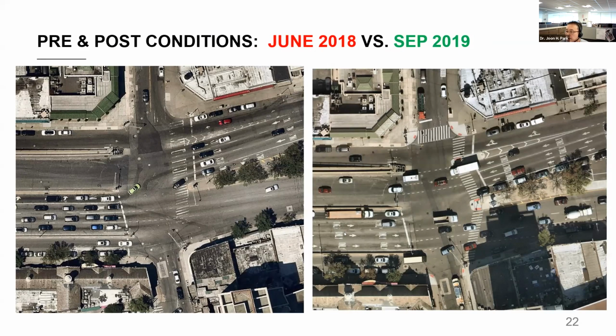This is a bridge location, so so much congestion creates a lot of other issues. That's why we are developing some alternative routes using the center median space. So this helps you with understanding. New York City DOT has 3 feet per second for elderly members, senior areas, and school areas. That is our standard. And for other locations, 3.5 feet per second.